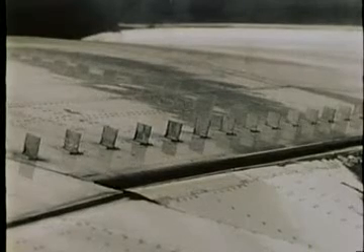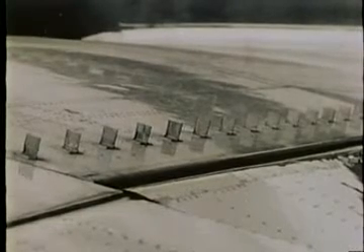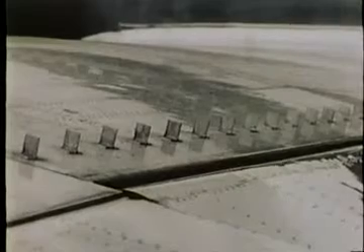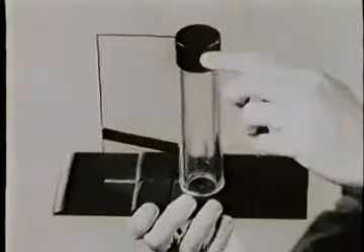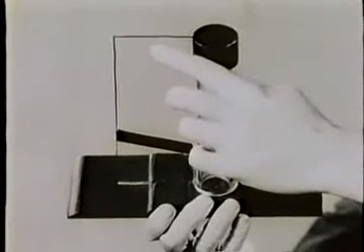In this film, we looked at flow along a flat plate and then saw the effect of pressure gradients on boundary layer flow. Now we can understand how this cylinder influences the flow on this plate. Without the plate attached, there is a static pressure increase along the stagnation streamline with a corresponding decrease in velocity.